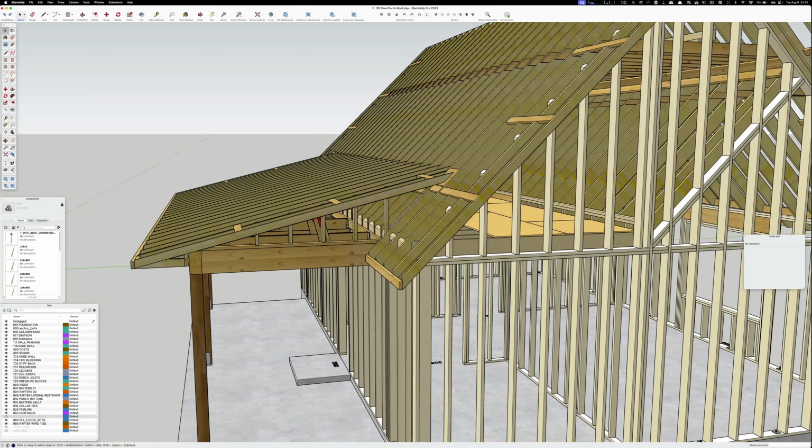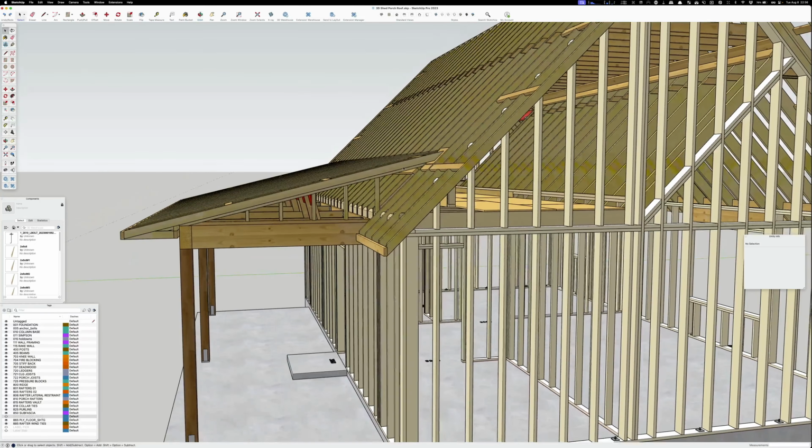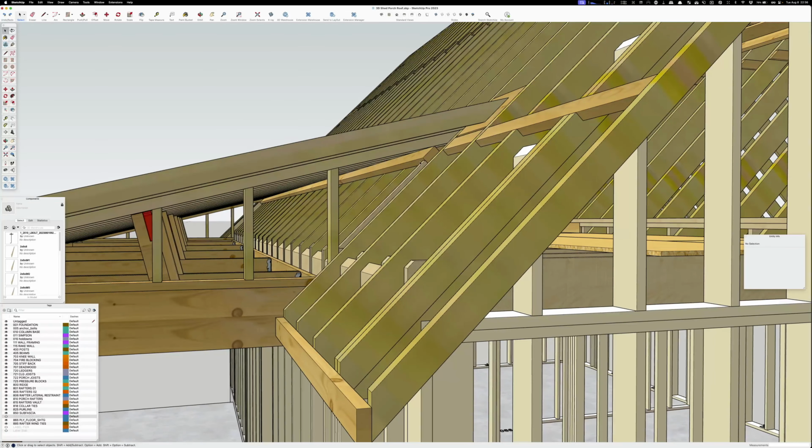But I like to calculate from the outside of the wall plate at the height of a plate along the rafter, come up, make a mark, and make the same mark at the other end. And now that all these rafters are straight, pop a line across here, and then put, say, 3 rafters, an outside one, a middle one, and an end one. And that will give me a nice level intersection point to where I could tuck a 2x4 like this, or a couple of them actually, up snug underneath those rafters so that this will support. And you shoot those, this is going to be a permanent board right here. Shoot those in, a couple nails to each rafter.